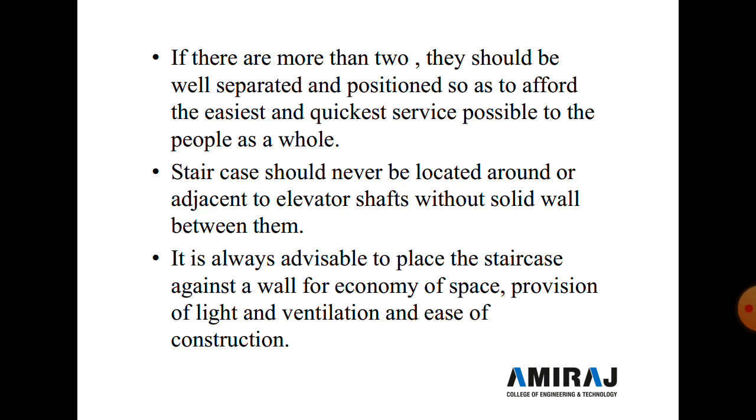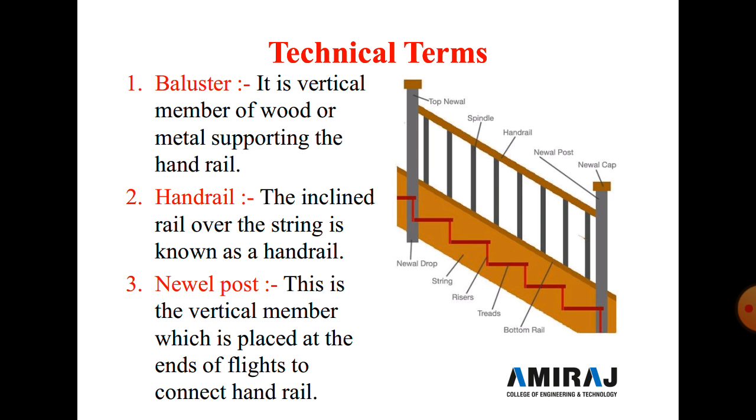Staircases should never be located around or adjacent to an elevator shaft without a solid wall between them, and it is always advisable to place the stair against the wall for economy of space, provision of light and ventilation, and ease of construction. Here some technical terms are given.